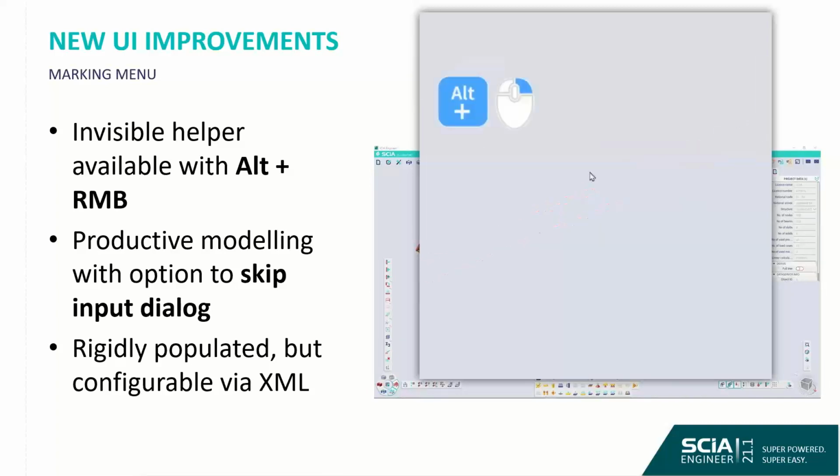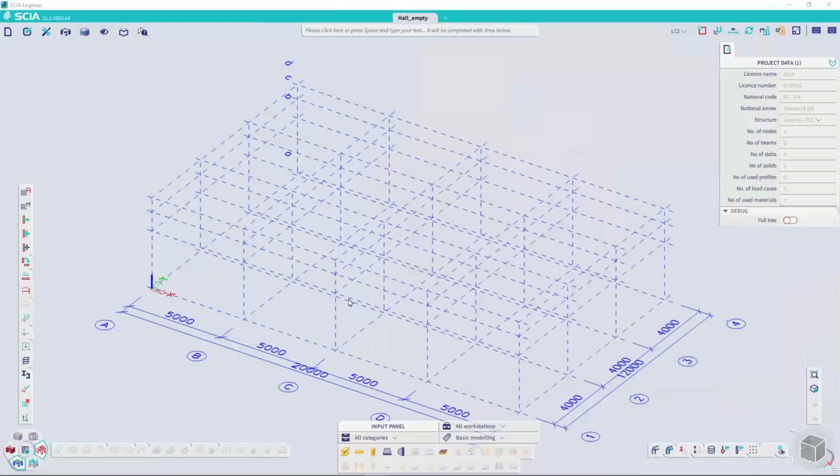And you can see that I didn't need to be precise on the button, because as the name marking menu implies, it only takes into account the direction in which your mouse moves. So if you just remember after a very short time that, of course, here the slab is going down, but slightly to the left, you are really able to remember these commands very quickly, and as I mentioned, to run them within a fraction of a second.